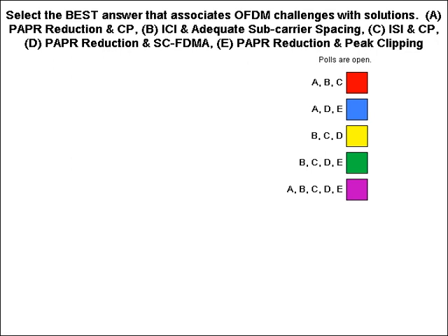And I will answer that question in the meantime. Cyclic prefix is added by the transmitter. So when the transmitter sends out a signal, it will add some extra time. And the easiest way for the receiver to process that signal is to just discard or ignore the first time period that corresponds to the cyclic prefix.